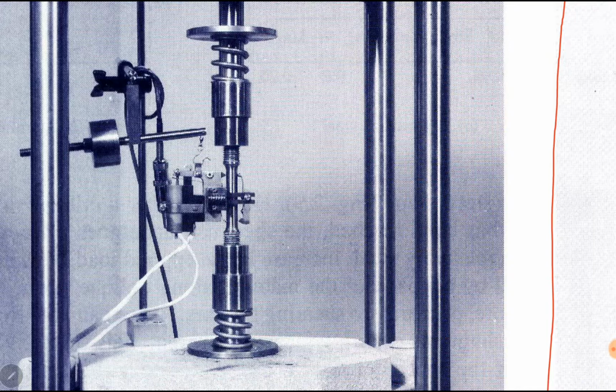First, we have to divide this steel bar into different portions to find the load in different sections. Because there are 3 loads, we have to section this rod between each 2 loads, after each change in area, after each change in load, and also after each change in material. There is no change in the material, so we section the rod after changes in loads and areas. So we will start from the free end.